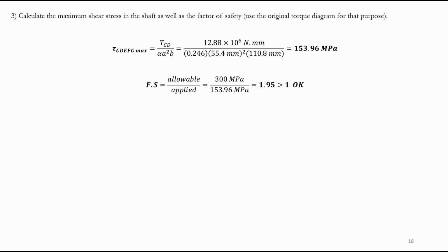After that, it was just a matter of applying the formulas based on the values we know from the torque diagrams, right? And after that, we found the power based on the power formula. Of course, we used the power formula based on shaft AB, which was the shaft through which the power was supplied.